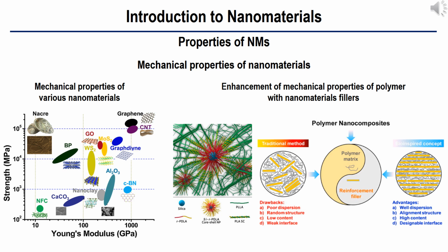The latter point is of special importance, as any specific advantages of a nanoparticulate filler may be lost if the filler forms aggregates, thereby mimicking large particles. Particulate-filled polymer-based nanocomposites exhibit a broad range of failure strengths and strains. This depends on the shape of the filler, particles or platelets, and on the degree of agglomeration.